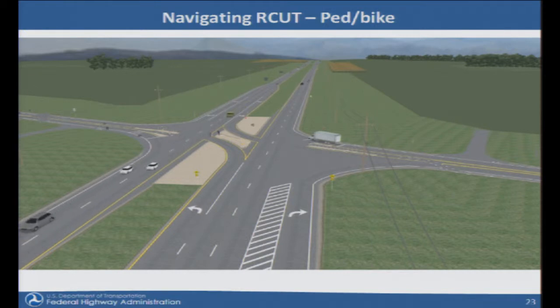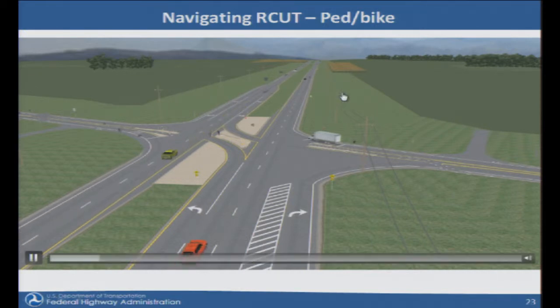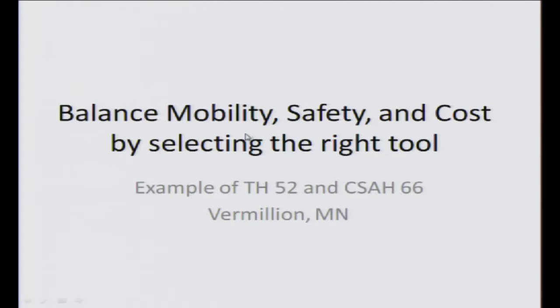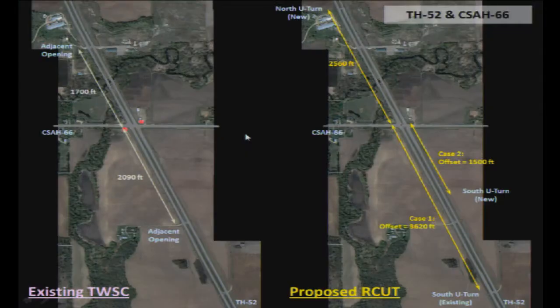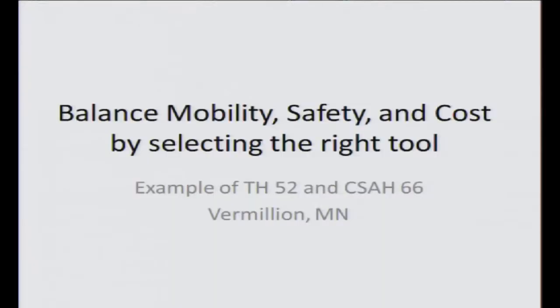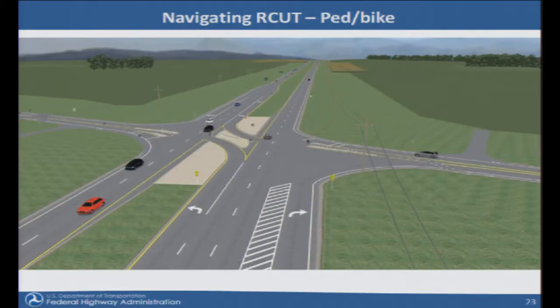The highest is 100 vehicles per hour from the minor road. So it's very easy to resolve the traffic conflict on the minor road. So basically, we'll provide something for the bicycle or the pedestrian to come here, and then in the protected area, wait for a gap, and go through. Okay, so basically, this video shows how a non-motorized user goes through the intersection.